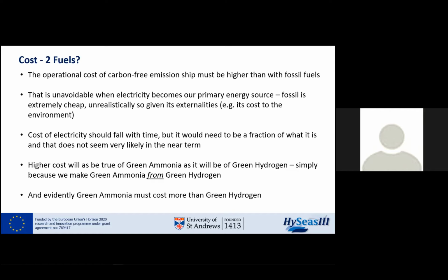You're also looking at a plant on a vessel itself to keep the hydrogen liquid. That's weight, and there's additional capital cost for that. So quickly you think, yeah, you can do this, but it's adding more to it. It's important that people do this so we get actual numbers on it. But this is part of the reasoning we've stuck to compressed hydrogen.